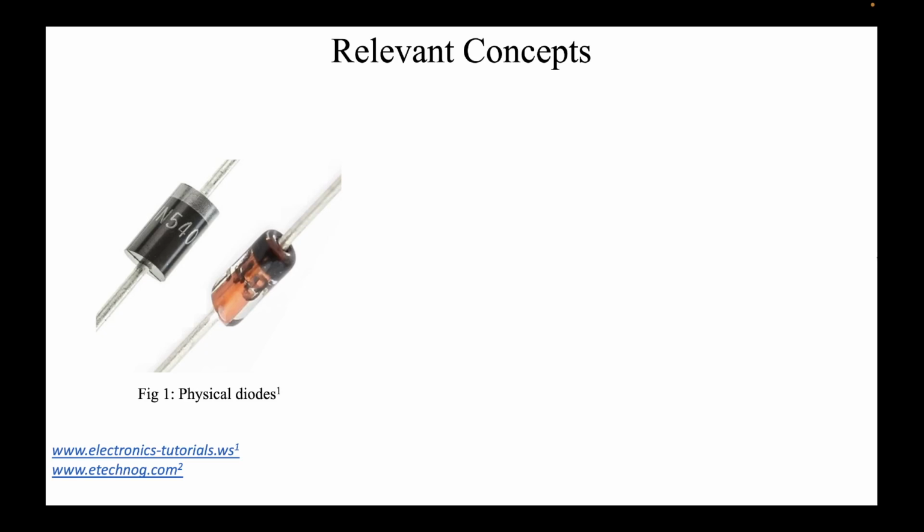So it has to be modeled if we want to use them in circuits, and we want to solve a simple circuit using simple KCL and KVL. We model them so that we can replace our devices. So what I want to do is replace my diode with a combination of, let's say, voltage source, resistance, maybe some capacitance, inductance and whatnot. We'll ignore L and C for now. We'll just see whether this simple humble diode can be expressed in terms of just voltage sources and some resistances, so that we can simply apply our KCL and KVL. This exercise is what we refer to as modeling.